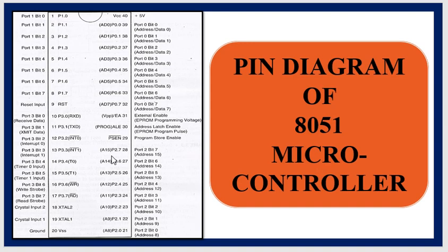And pin number 29 is called PSEN. If external ROM is used for storing a program, then a logic 0 appears on it every time the microcontroller reads a byte from the memory. So PSEN means program store enable.